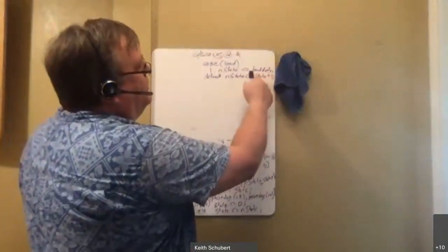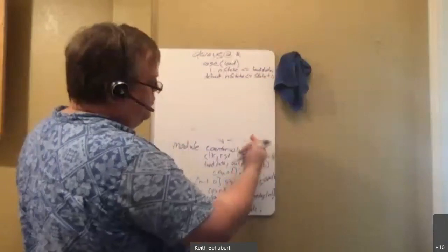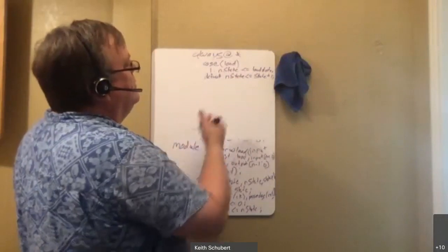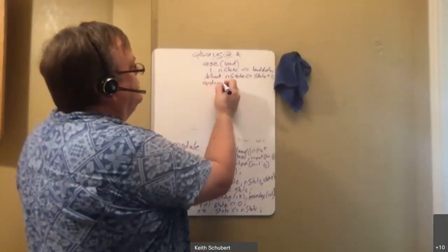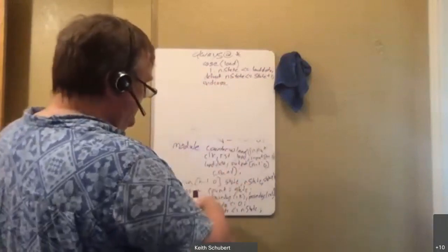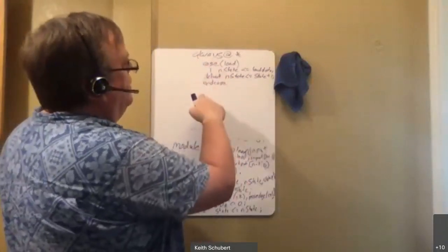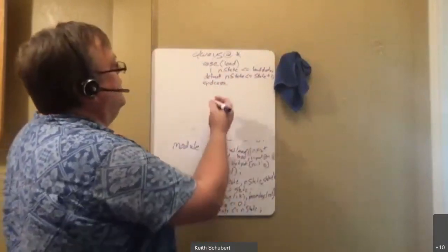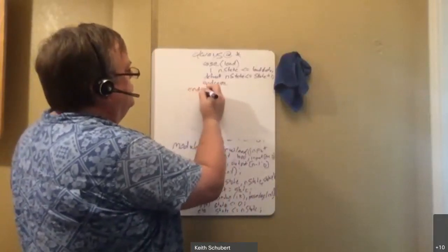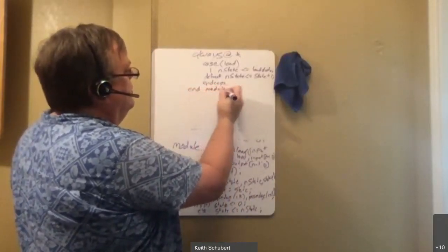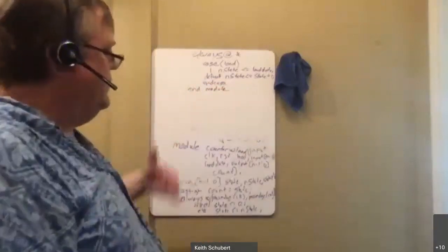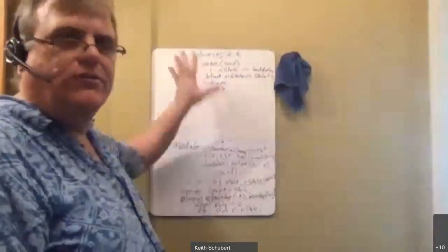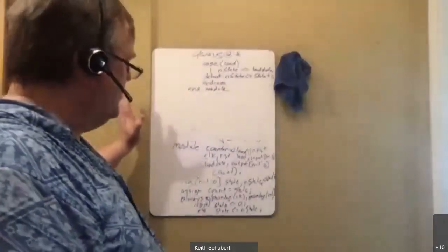So the output of this technically exists and is the state plus 1, but I never need to call it because I just combine it and send it over here. Right? And then I can just do my end case. Right? The always doesn't need to be ended because this is technically only one line, just like this is an if statement, so it's technically only one line. So then I just have to end my module. And then I would actually have a nice counter that has a load built into it. And I could use this. So this is Verilog code that will work nicely to handle everything else.